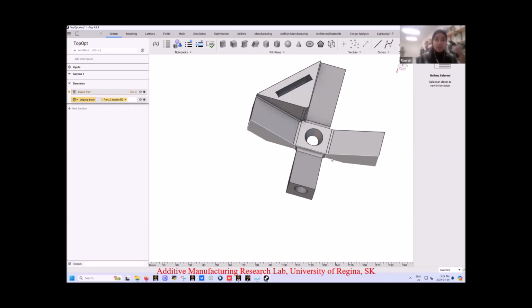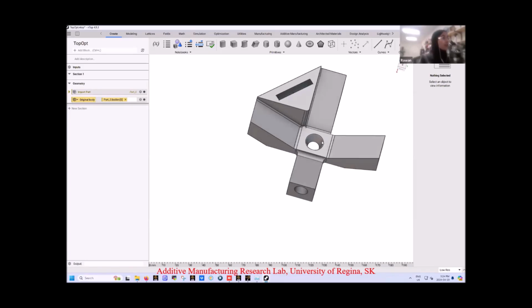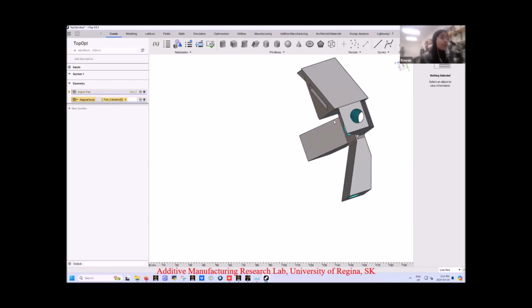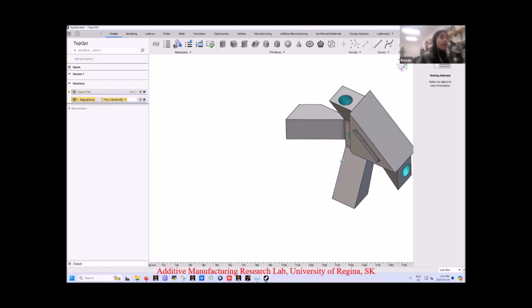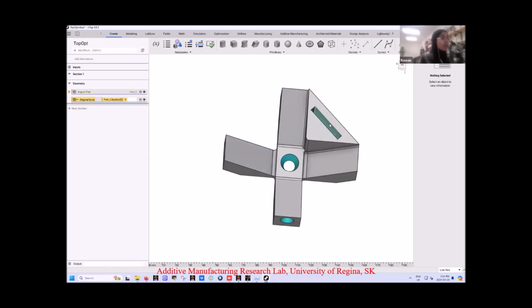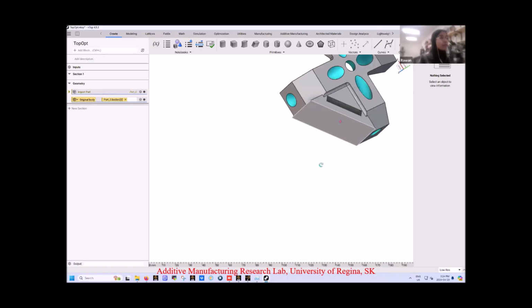And the other one is to specify each face by itself, which will help us later on in the boundary condition selection. So let's start with identifying the faces that we want. So I want this one. I want, of course, the four legs to not be touched, and these will be our interfaces. And of course, when I hang the bracket, this face will be touched, as well as this part, which will be in direct contact with the hanging structure or the linking bar.